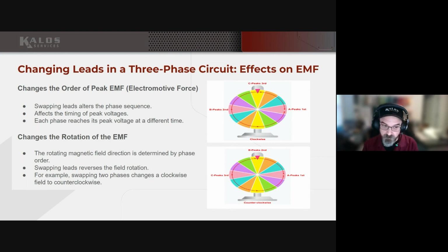That's how that works. The theory is kind of neat, but if you're in the field and you just want to reverse a motor, you don't need to know the theory. Just know, okay, in order to reverse this motor, I need to swap any two leads. And if I have a VFD, I have to do it on the load side of the VFD. If you take nothing away from this, if you know that much, then you'll be able to get that equipment running the way it needs to.